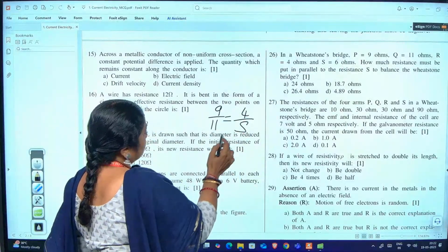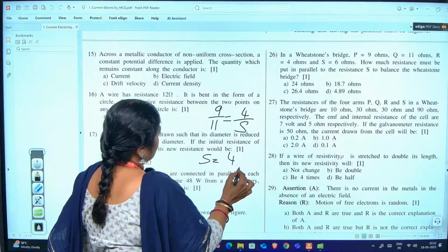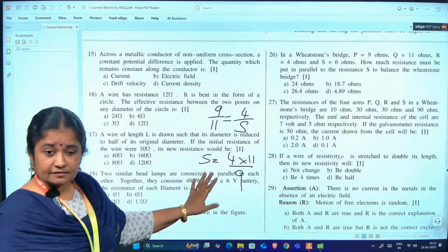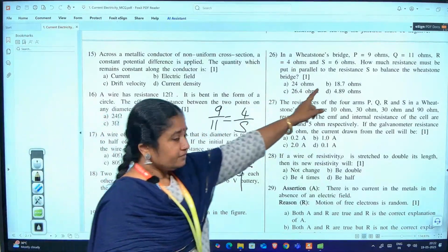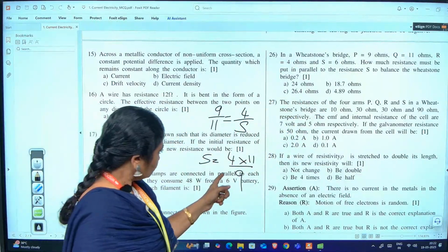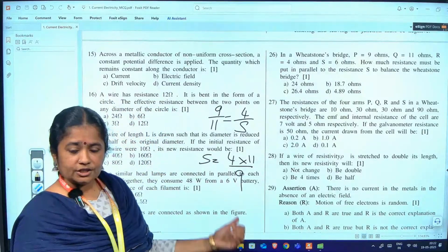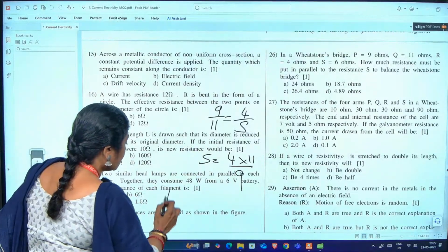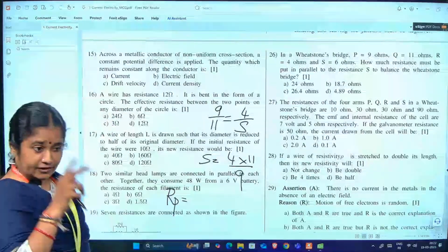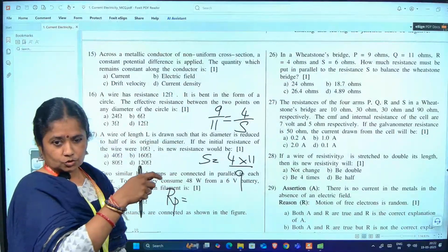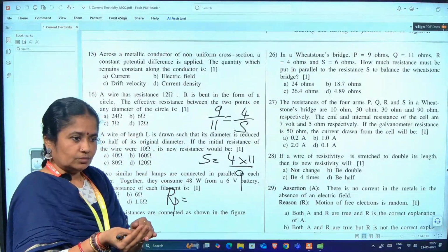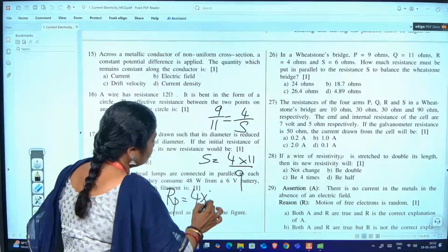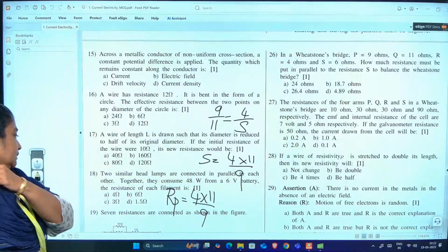Now, when you cross multiply, so this should be your effective resistance. But there is already a 6 ohms there. What should we convert this 6 ohms to? 4 into 11 by 9. What should I put in parallel for that? So the effective resistance, that is RP, is the net effect of the two resistances. To the 6 ohms already present, I must put some amount in parallel, right? Together they should give a total of 4 into 11 by 9, that is RP.